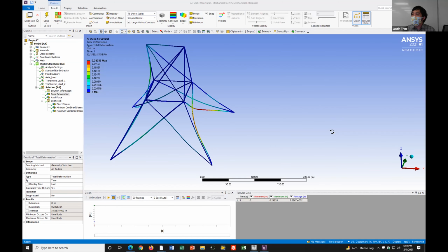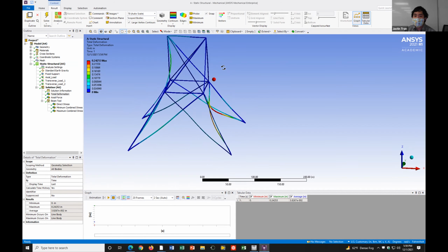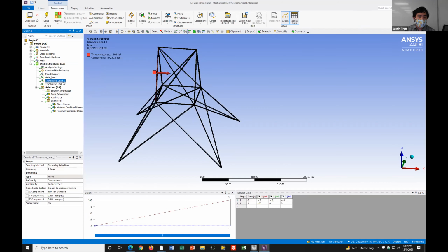All right, how's everyone doing? Everyone can see the stress stiffening effect, right? This is a bigger example of the beam case that we talked about on Monday. We're keeping the transverse modes exactly the same, so those are not changing. For the axial, the only thing we're changing is how much axial load we're putting on this. If you compare the results for when you have the truss at maximum tension, which is when we apply an upward 10,000 pounds,